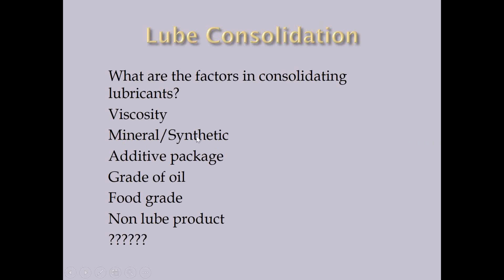But again, as long as it's a PAO synthetic and it's roughly the same viscosity, you can mix PAO synthetics and mineral oils. Make sure you find out what the additive packages are in there. Sometimes there are additive packages that you won't be able to consolidate. One of the customers we had in the Washington, D.C. area had 22 different oils, and we were able to consolidate down to 10 different lubes because we switched everything to synthetics. Synthetics cover a broader, wider range, and there are fewer additive package issues.